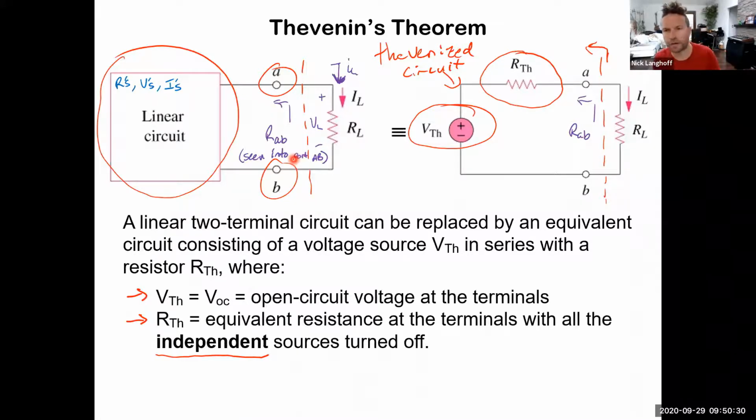And the load needs to be disconnected as well, right? Because otherwise you're measuring it in parallel with the load. Okay.